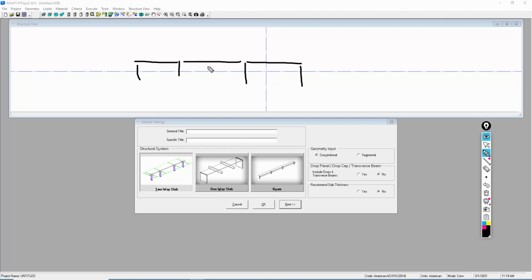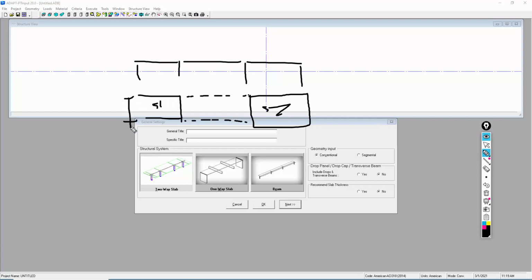And if I kind of flatten this out in plan view, what we're going to have is a prismatic span in span 1. Span 2 will have a prismatic span. And then in span 3, what we want to do is we're going to say that originally this particular strip was also the same width. We'll call this W here as span 1 and span 2. We'll call this middle span. But there may be a need to puncture the slab, put a new opening in, and then we need to determine the new capacities for the section. So we're going to say that the opening will be here.